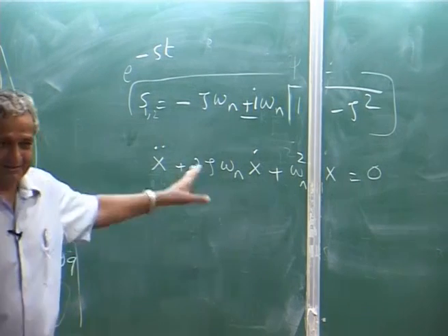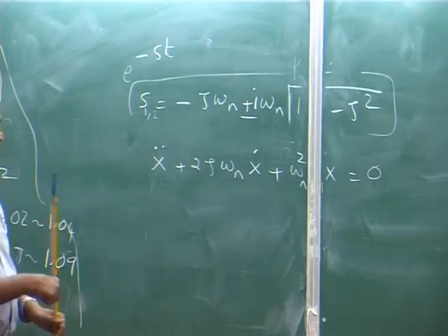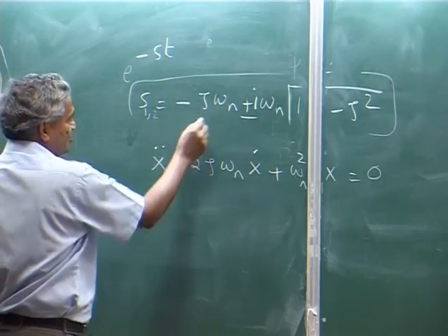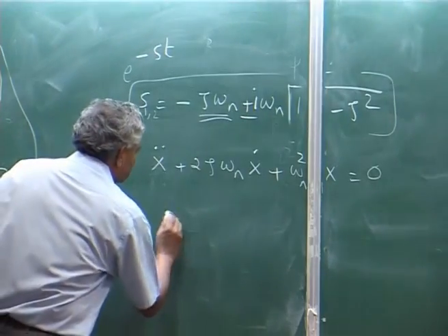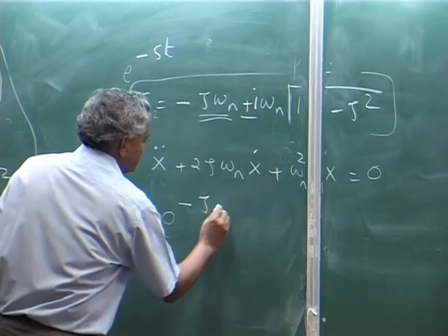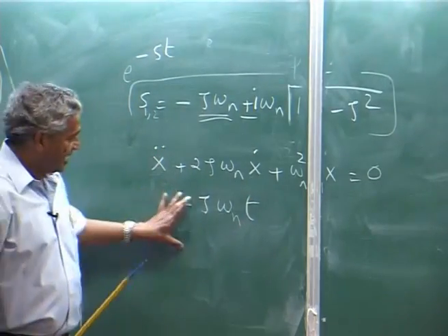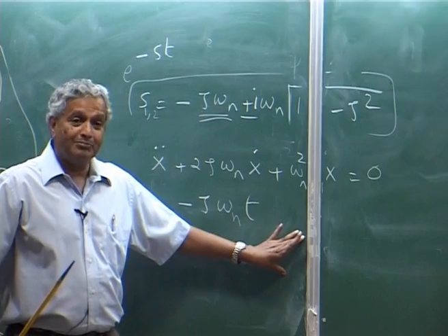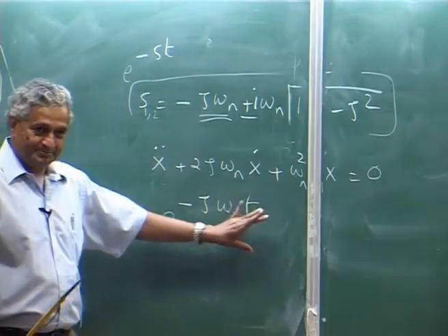This is a simple single degree of freedom damped system solution. So, the damping here, if I substitute, is zeta omega n. So, e to the power minus zeta omega n t is how my amplitude will decay. This is the decay term.